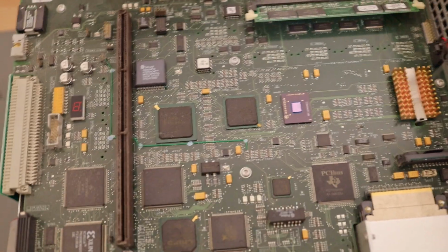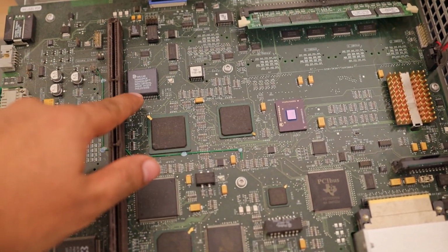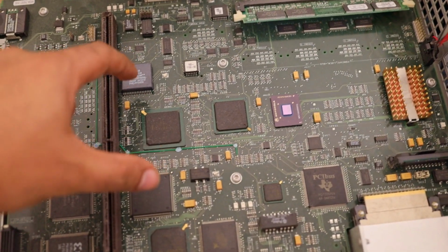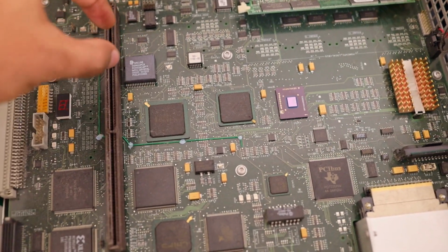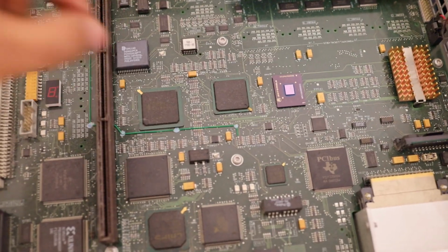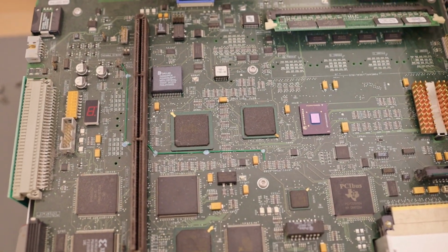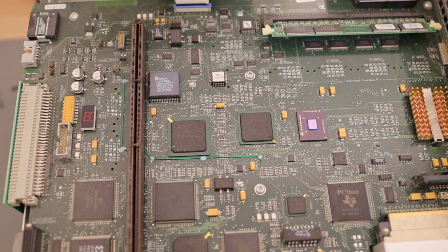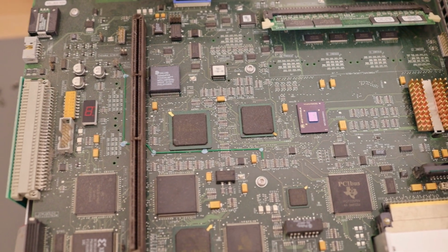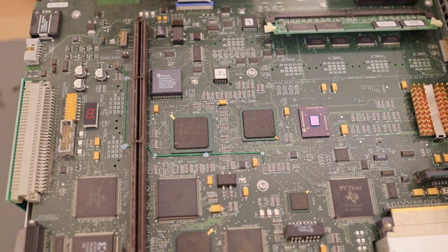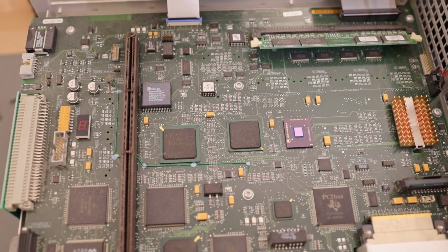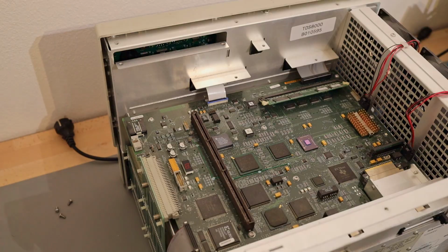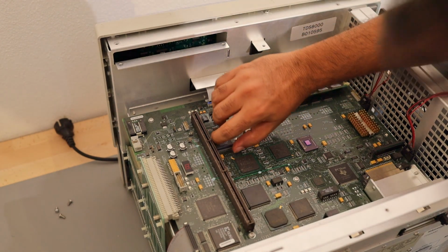You can see this is all messed up, and as I said before, this is the RLS chip which has memory and battery. This little thing is the battery on top of the chip or the module, and that's where all the configurations are saved. We will try to first change the battery, and then we will try to figure out if the chip is faulty. If the chip is faulty, then we need to change the whole chip. So let's try to take the battery out.